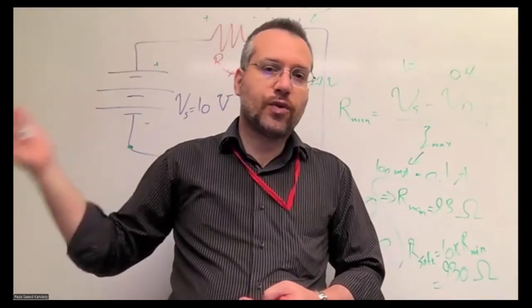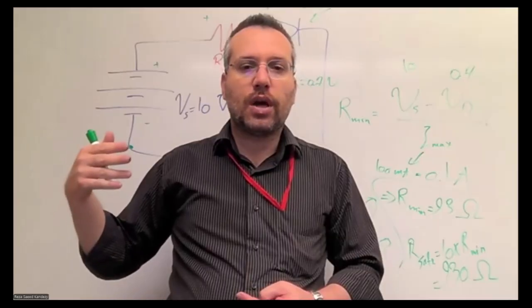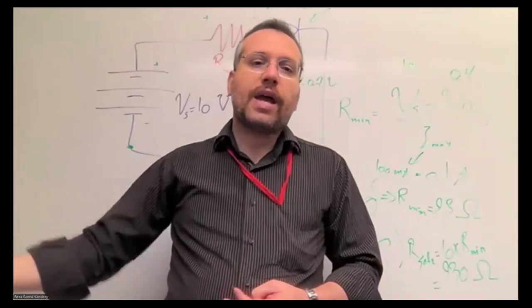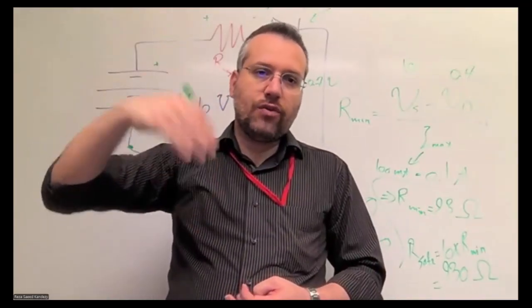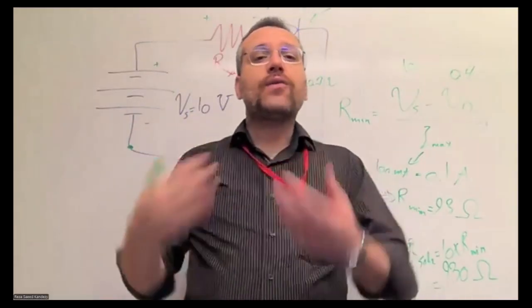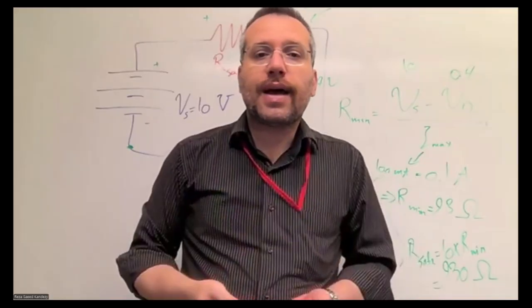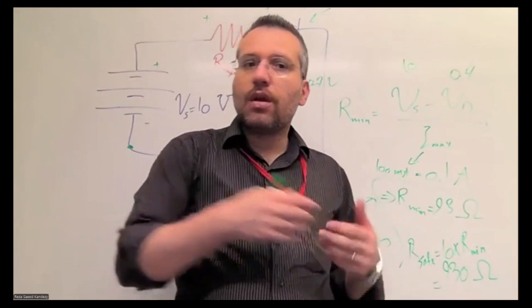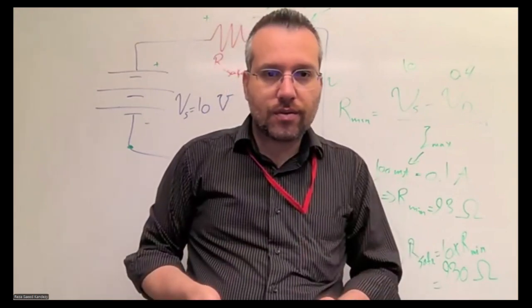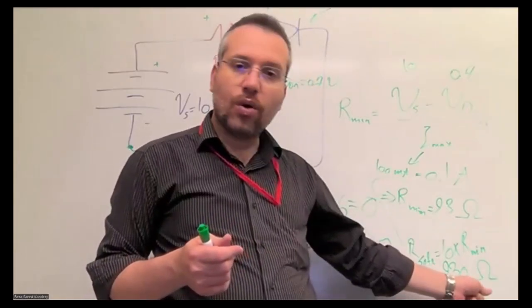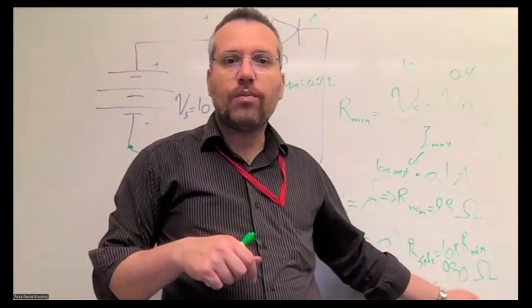The diode is also forward biased, so we have a forward voltage drop for the diode. And we consider the worst case scenario, which is the maximum current rating for that diode. After that, we multiply that value by a safety factor. We consider 10 as a safety factor for extra protection, which gives us 930 ohm, close to 1 kilo ohm.